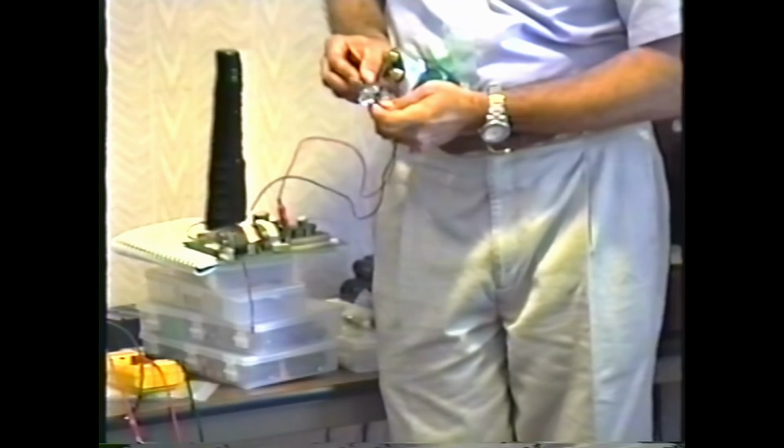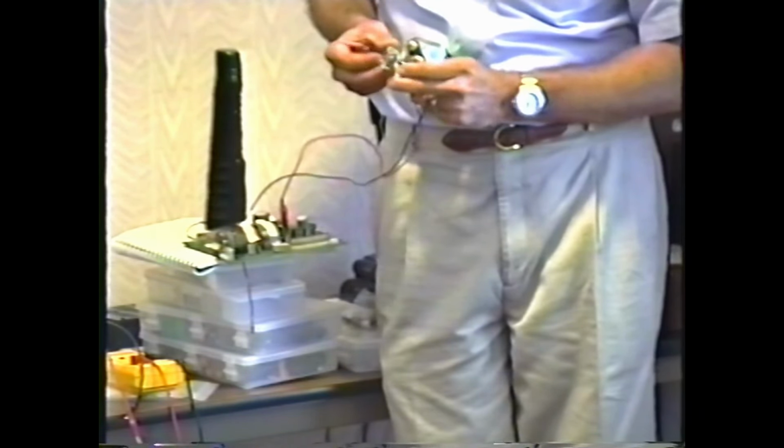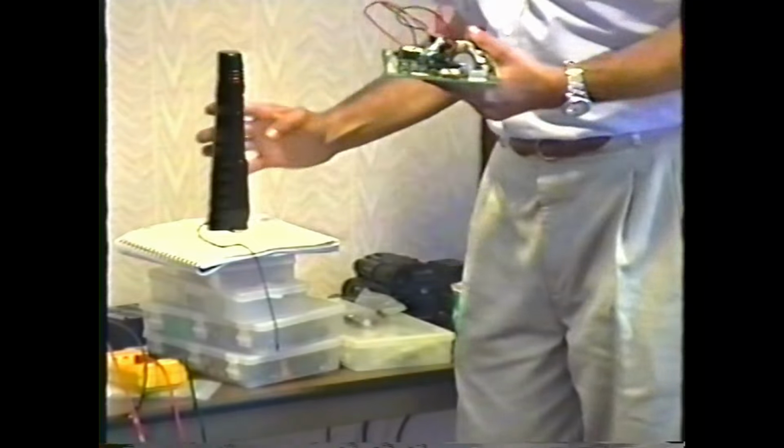Now when I connect the lamp to it, what you'll see is the lamp will glow for a short time and then dim out as the capacitor discharges. Here, let me just do it one more time. Charging up, discharging. Capacitor charging up, discharging. And actually, if I don't charge it through the lamp, if I charge it just directly off the battery, that's all it takes. Just a fraction of a second will completely charge the capacitor. So a capacitor is like a very short-term rechargeable battery that can be quickly charged up, but will also just as quickly discharge.